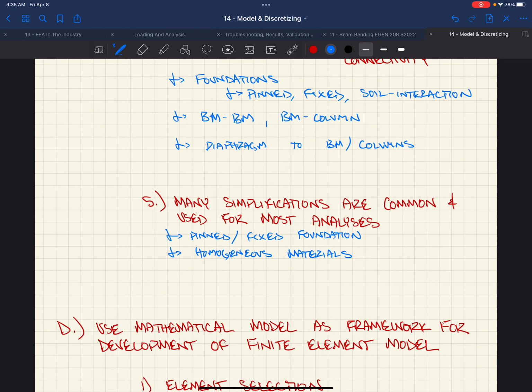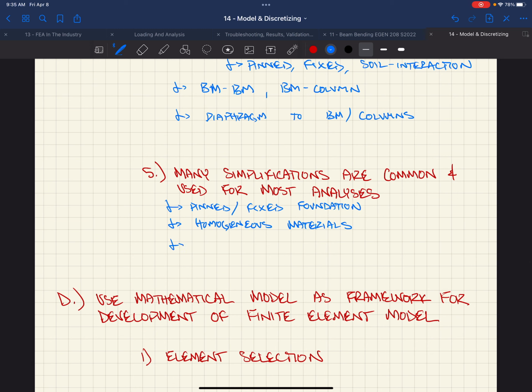Homogeneous materials, what's something that's not homogeneous that we design all the time? Wood. Concrete, right? We make this assumption that it has this nice modulus of elasticity throughout its entire length. It behaves homogeneous even though it does not. Concrete, we make some simplifications for it's going to crack. Well, that's going to change its section properties, right? But again, we assume that section property is consistent throughout its whole length, even though we might get a crack once every 5 feet, I don't care. We're going to say that everywhere it just smooths out in the end, right? So it's a huge simplification.